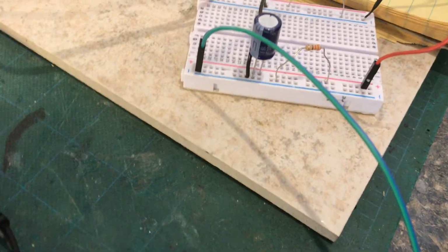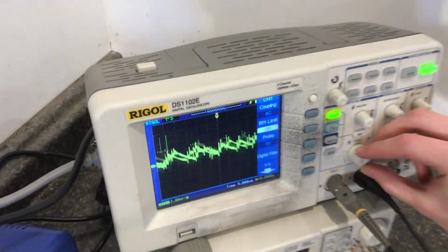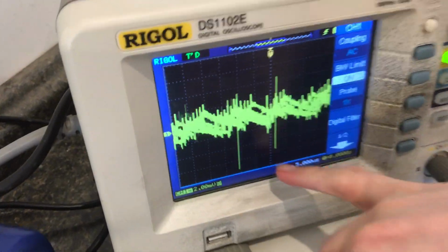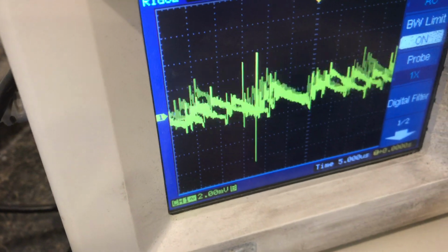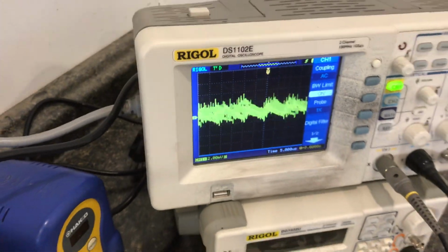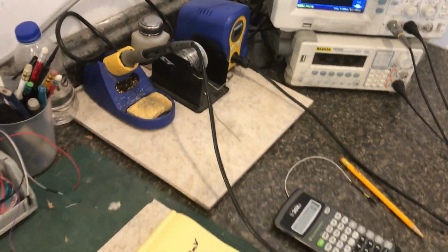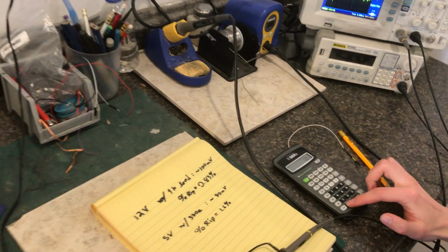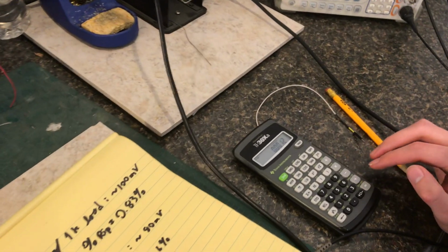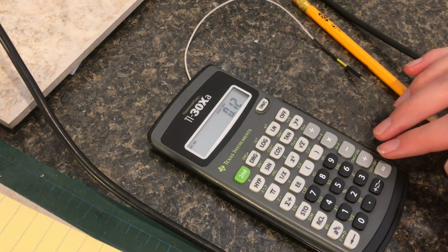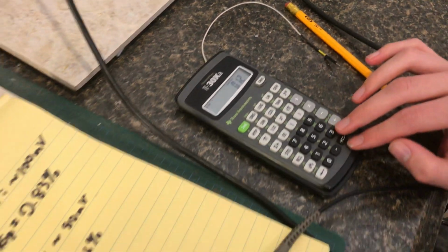That's kind of a large capacitor. Well, let's measure it now. It's still there, it's just smaller. Ugh. That's a 2 millivolt grid. So I'll call it 4, 5 maybe. I mean, a generous 6 at most. So with the capacitor, 6 millivolts. I mean, that's nothing. 0.12%. So that's hardly anything.